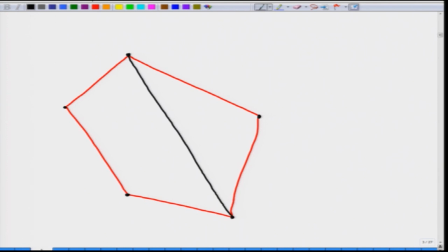Suppose the length of your reference line is, say, 100 meters. So, we will say that this is 0, this is 100, and now you start moving from 0 towards 100, and you reach the first point. What you have done is that you have added stakes on all of these points for which you want to take the measurements, and now you are moving from 0 to 100, and you reach a point where you find out that the first point is exactly to your left. So, it is making an angle of 90 degrees, and you now have reached this position. This is your first position, so let us call it position A.